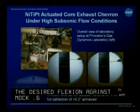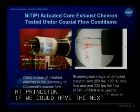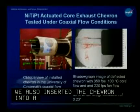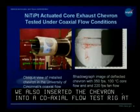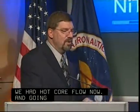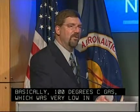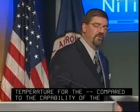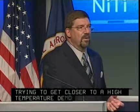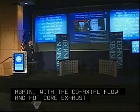If we could have the next slide. We also inserted the chevron into a coaxial flow test rig at the University of Cincinnati, so we had hot core flow now going across the chevron, basically 100 degrees C gas, which was very low in temperature compared to the capability of the alloys, but it was the highest the rig could throw out. But trying to get closer to a high temperature demonstration, again with the coaxial flow and the hot core exhaust, we were able to generate the required deflections for the material.